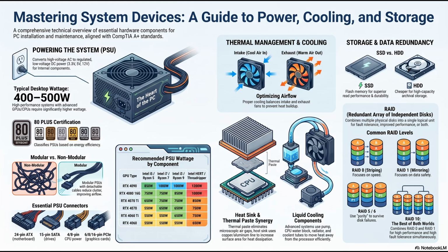Speaking of keeping things cool and running efficiently, our source points out a physical design choice in PSUs that directly impacts system health: modular versus non-modular cable. The non-modular power supply is the traditional design. Every single cable, the 24-pin, the CPU cables, the multiple PCIe and SATA tentacles, is permanently soldered into the internal circuit board and exits the metal housing through a single hole. This means if you are building a relatively simple computer, maybe just one hard drive and no massive graphics card, you still have 6 or 7 thick cables permanently attached that you don't need, leaving you with the frustrating task of trying to stuff those extra unused cables into the empty cavities of your computer case.